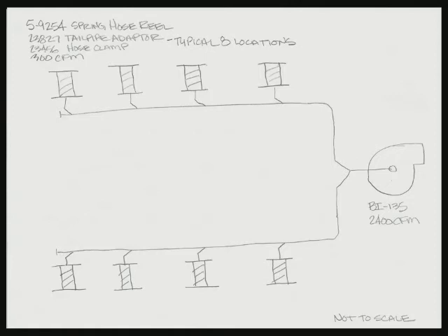I guess we have 2 ways to approach that. One would be if in this particular facility they did not know exactly where the higher performance vehicles or the larger engine vehicles are going to be. Let's just take this picture as an example. If the larger vehicle could be in any of these 8 bays, we're going to have to size the hose reels for the larger vehicle. We have to be able to cover the largest vehicle in any bay. The other option would be to set aside certain bays for the larger vehicles and make the rest of the bays for the smaller vehicles. That way we can size the bays for the larger vehicles with the appropriate CFM for that vehicle, and the rest of them will remain the same.